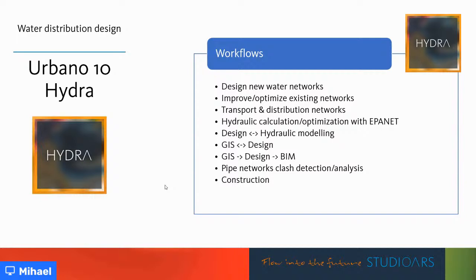So various options. You can also go in the direction towards BIM. So with Urbano Hydra, you're actually working on a 3D model all the time. Even when you're working in the plan view or the long section, you are actually editing the 3D model. So it's then not a big problem to export it to IFC or to Navisworks. And there's other workflows, of course, as well.